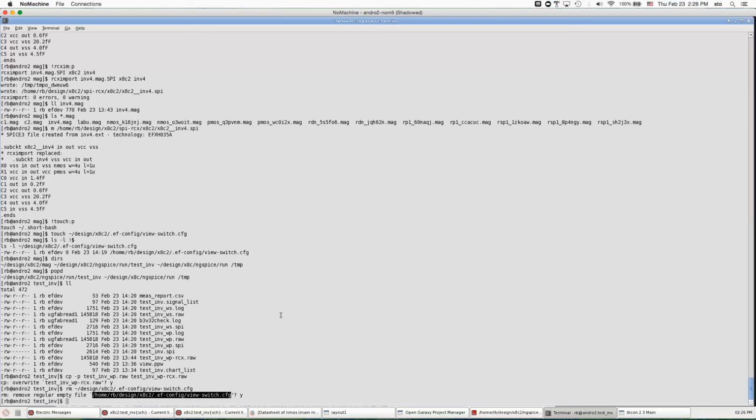Okay. If I'm working on the schematic, I edit the schematic and I netlist, and I have an RCX view and this control enabled, then it's going to overwrite your raw files. But I may see no change. I run the simulation, I look at the waveforms, I see no change. What's going on? Because I'm expecting that my schematic change will have an effect on the waveforms, and it won't, so long as it's still swapping in the layout-based netlist.